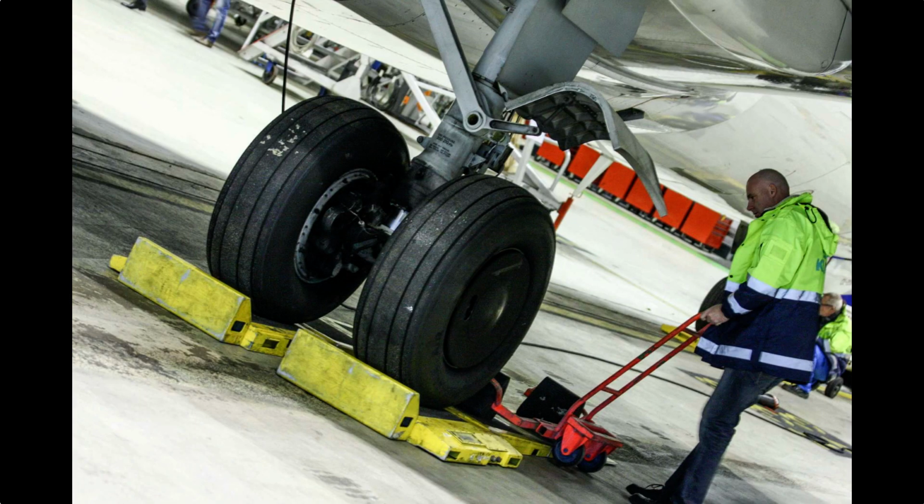Requirements. Regulations do not require periodic weighing of privately owned and operated aircraft. Such aircraft are usually weighed when originally certificated or after major alterations that can affect the weight and balance. The primary purpose of aircraft weight and balance control is safety. Manufacturers conduct extensive flight tests to establish loading limits for their aircraft because limit information is critical for safe flight. A secondary purpose is to aid efficiency during flight.